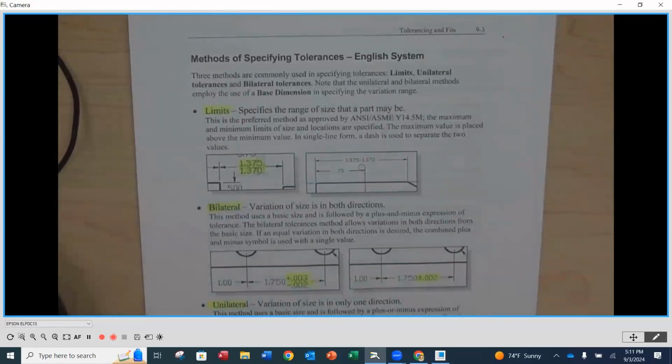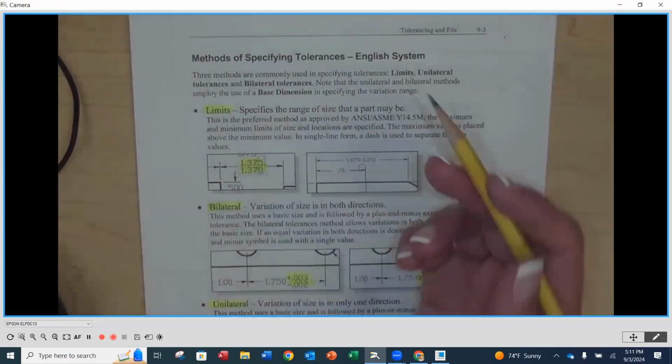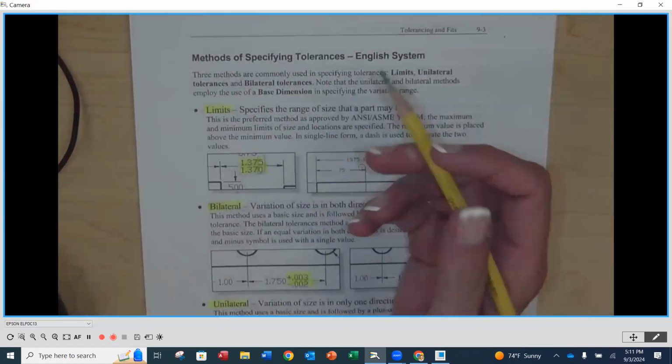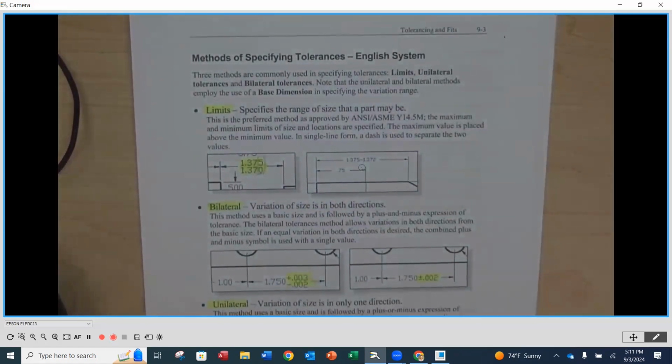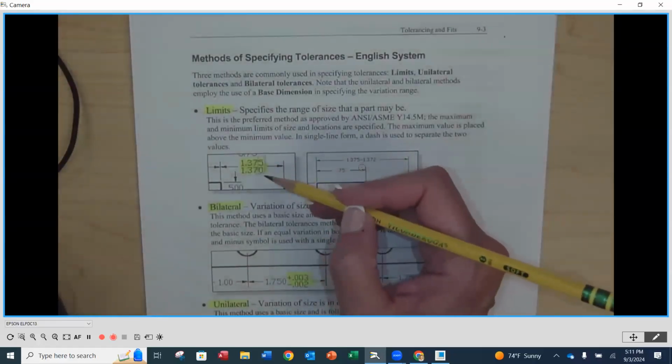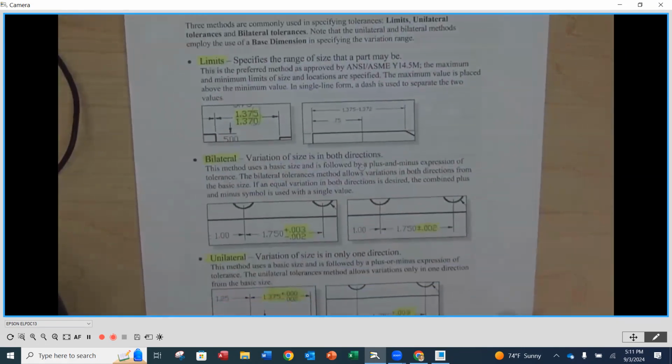Okay. So when we talk about 5 thousandths, it's 0.005. If we say 2 thousandths, it's 0.002. All right. If it's 5 tenths of a thousandth, it's 0.0005. Okay. So when we talk about tolerancing, a lot of times we are referring to that thousandths place. And then here we can see the limit dimensions. Most often we're going to see limit dimensions that are upper and lower to one another. So when we're in our CAD software, whatever it might be, SolidWorks, Creo, AutoCAD, we can play with the settings to achieve this. And we'll see it in application on drawings that we have coming up.